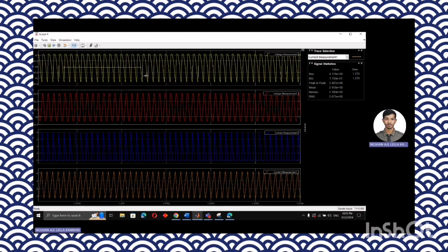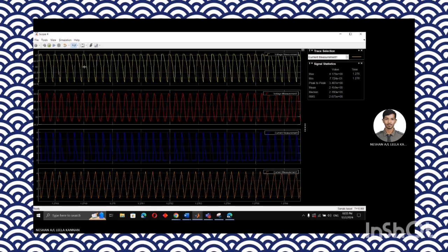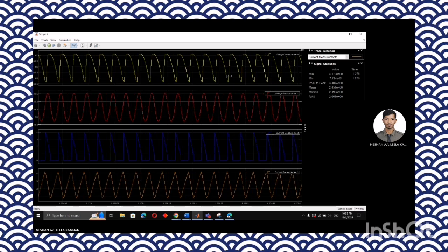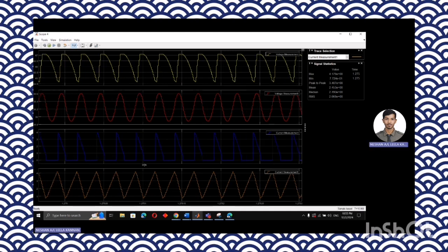Make it nice. So as you can see the waveform, which is okay. This is VS. So this VO, when the Vin is going up, the VO is going down, and when the Vin is going down, the V output is going up. The waveform looks like a sawtooth waveform.